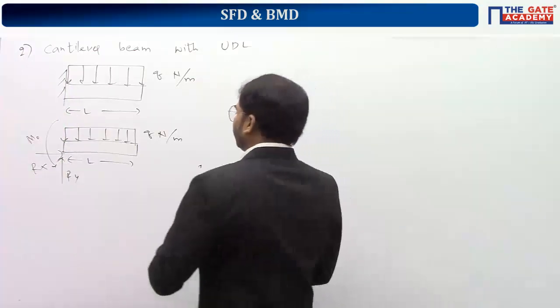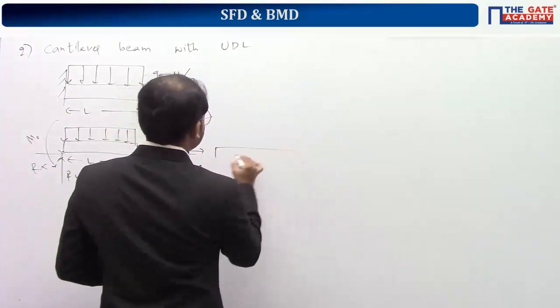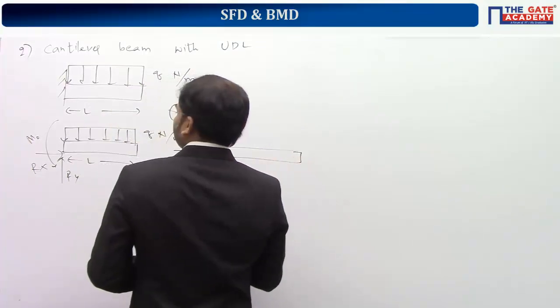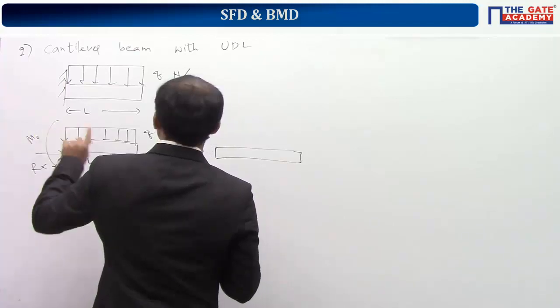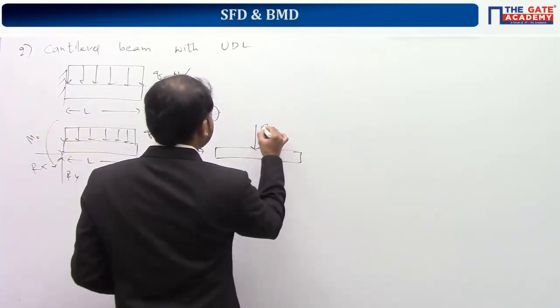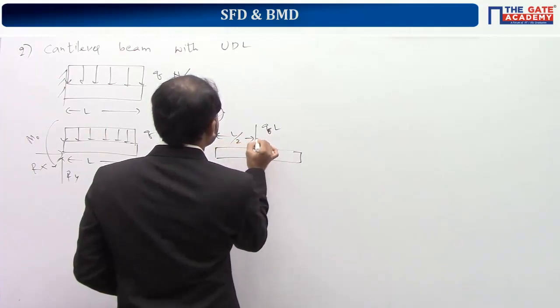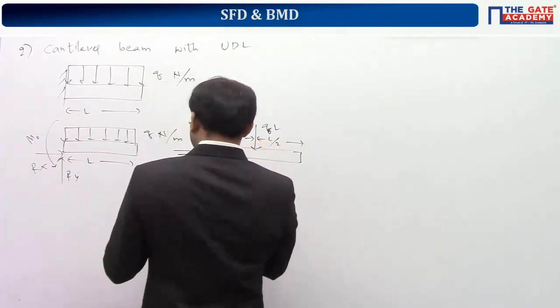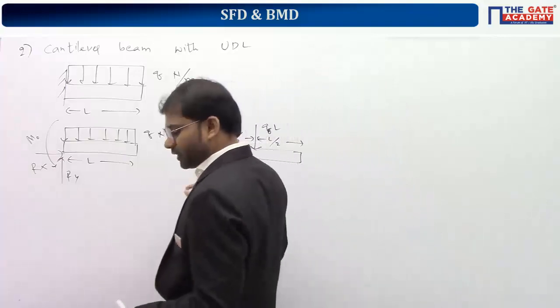So actually while dealing with this, what you should do is you should do one extra step, that is you should take an equivalent load. So this q is a uniformly distributed load acting like this. So it is nothing but a point load of magnitude q into L acting at a distance of L by 2 from both the sides. So we are taking this equivalent load here. It becomes easy to deal with this. So how we should take equivalent load?